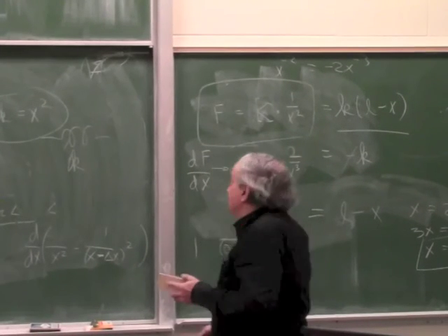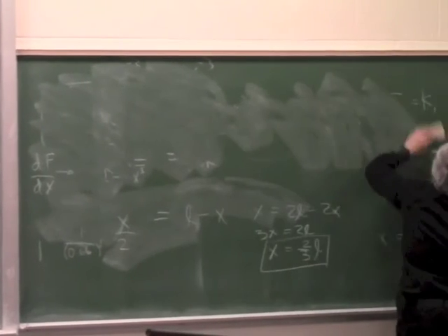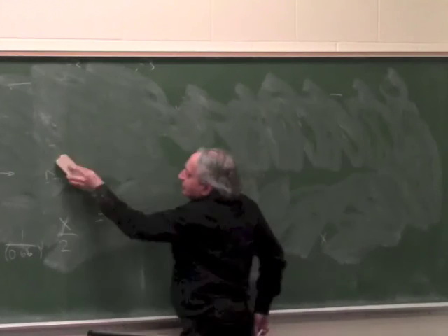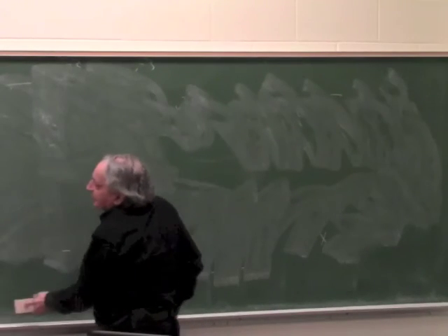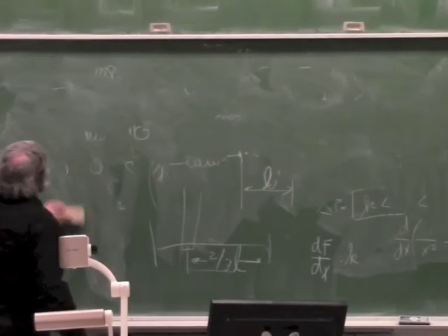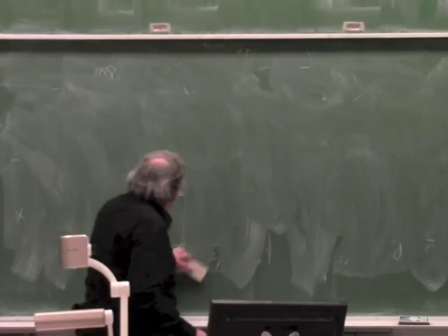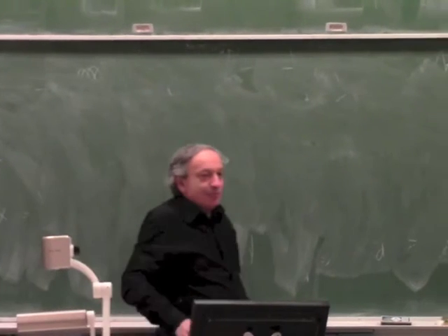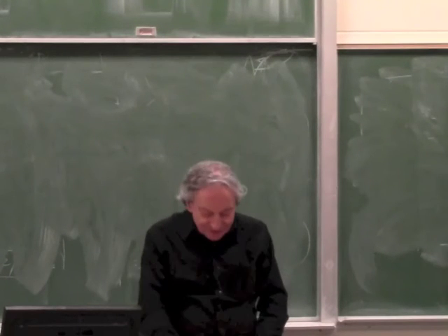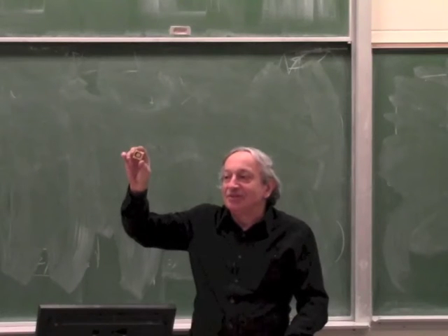I talked about electrostatic actuators, and I said that when things are very small, the force of electrostatic actuators can be as big as magnetic actuators, and that's why they are very common in micro-machined devices. I mentioned that the most popular electrostatic actuator in the world in terms of units made is this thing, the DMD or DLP.